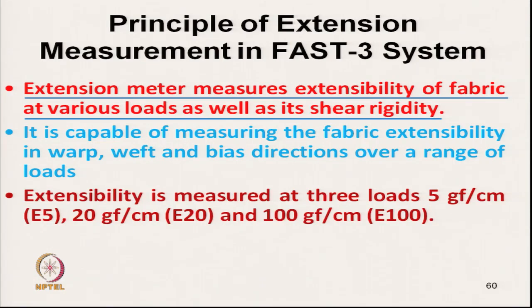The extensibility is measured at 3 different loads: at 5 gram force per centimeter, which is known as E5, at 20 gram force per centimeter, E20, and E100, which is 100 gram force per centimeter.